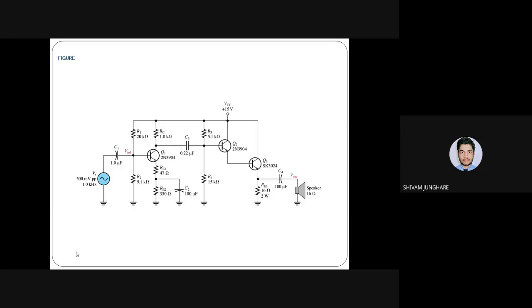Now, suppose the operating point is selected below the center and above the x-axis on that DC load line. So take this second consideration, that the operating point is selected below the center and above the x-axis, and try to find out how much VCE will be on the x-axis. Here I can say the obtained VCE will be greater than 7.5 and less than 15 volts. Do you agree with this?